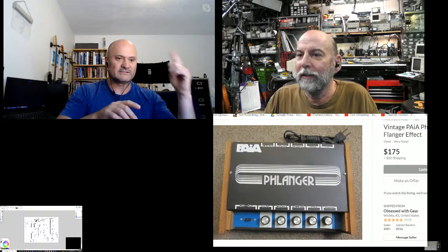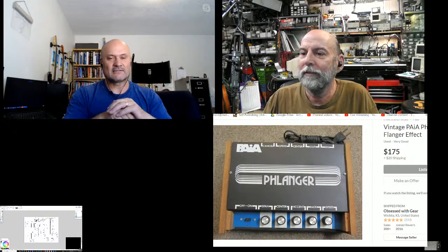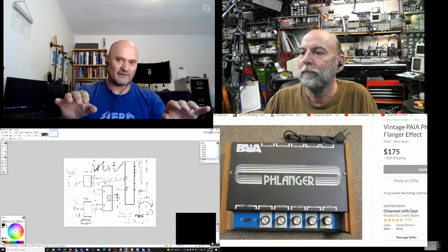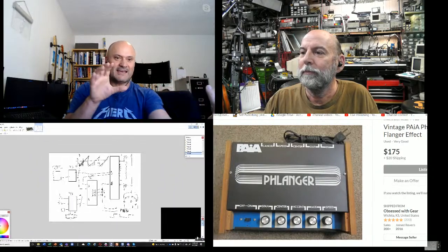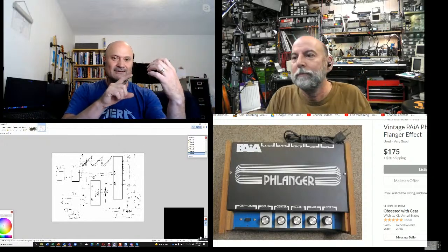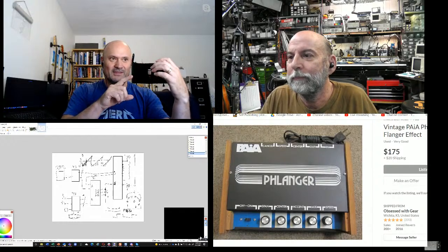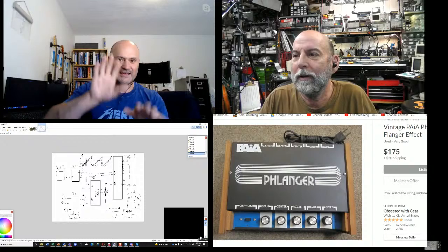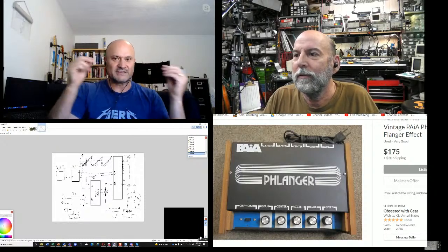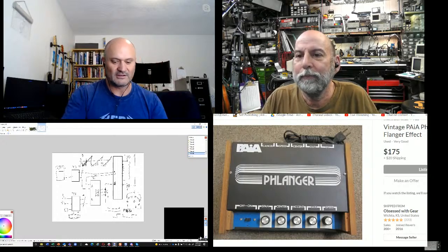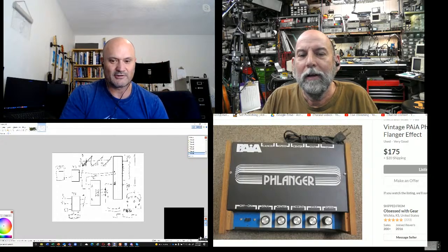And so one's speeding up, and those low frequency oscillators are also driving a voltage controlled amplifier on the output of each one. So as it effectively comes towards you, it's going up in pitch, but it's also getting louder. Then it goes down in pitch and gets quieter. And all of that's done out of phase, and you take a stereo output of the guitar effect, and you get this stereo sound spread that's incredible.